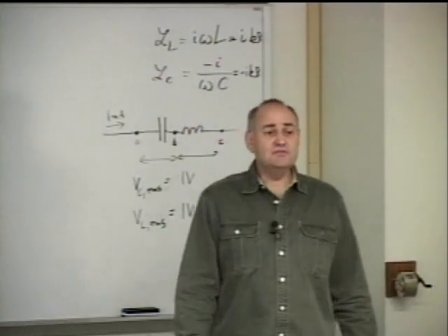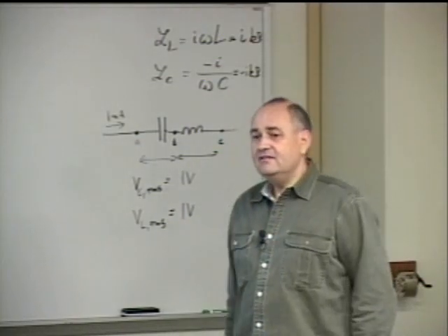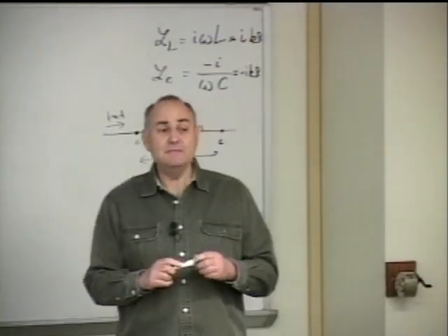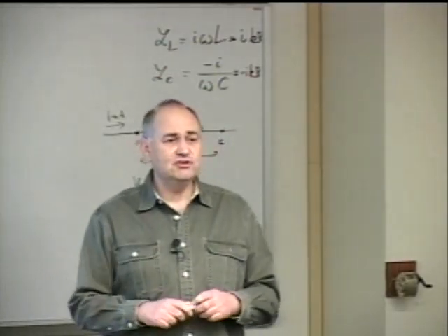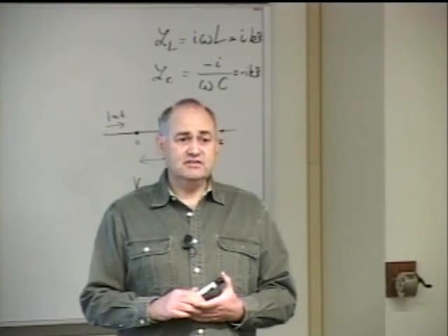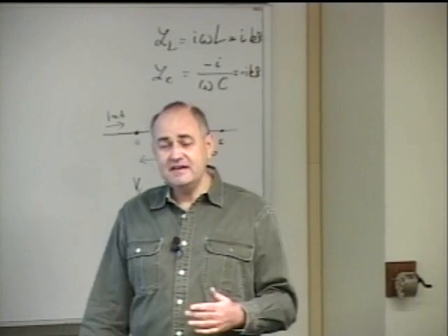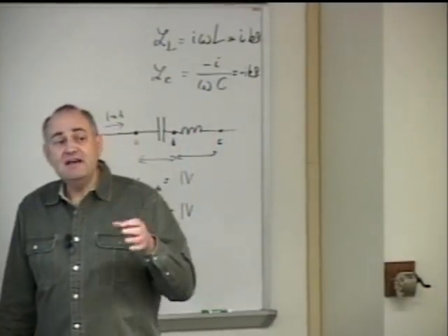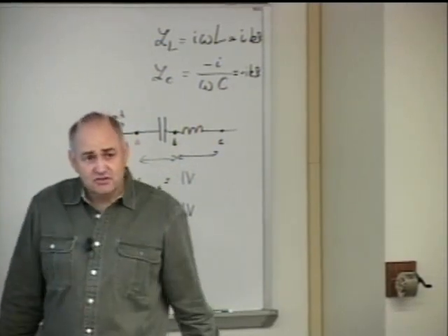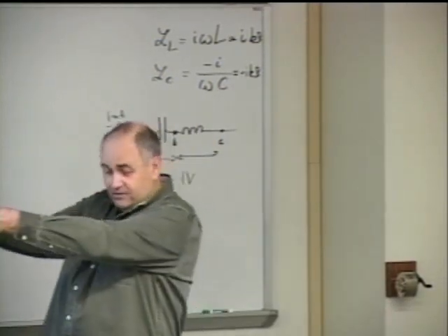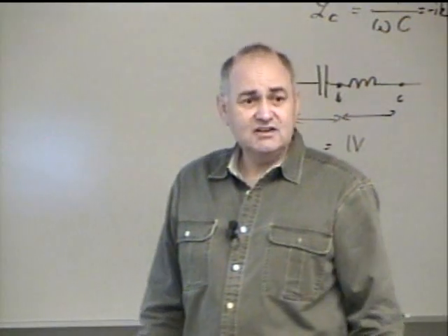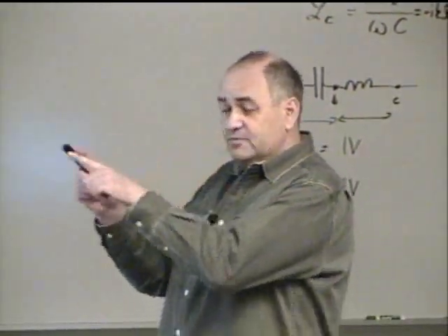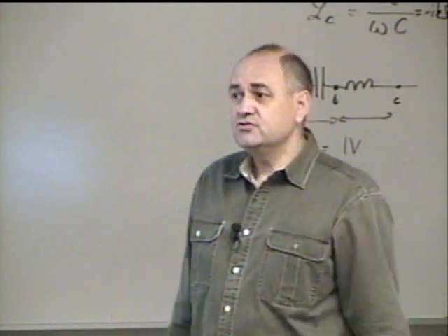All right, so root mean square values are 1 volt. If we use a meter, a voltmeter or an ammeter, the scales are always made in such a way that they measure root mean square values. So if you buy a meter in an electronic shop and plug it into the socket, it will measure 120 volts. This 120 volt is the root mean square value. It always measures root mean square value.